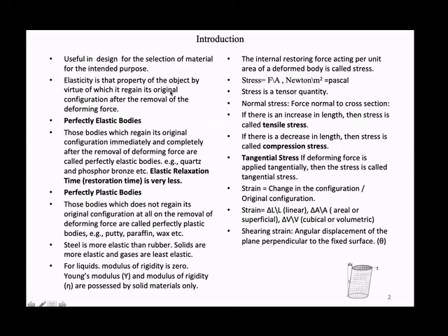Elasticity is a property of an object by which it regains its original configuration after removal of the deforming force. If I apply a force, we are all talking of rigid bodies. Rigid body means it does not deform. It's not that it will never deform. If the force is more than its capacity, it will definitely deform and lose its configuration. But there is some stage where it can tolerate that load and it will come back to its original configuration. That is the property of elasticity.